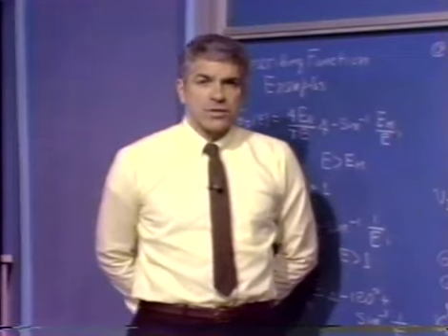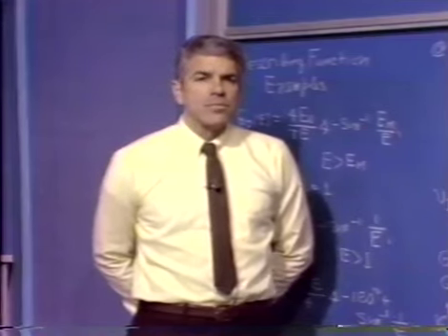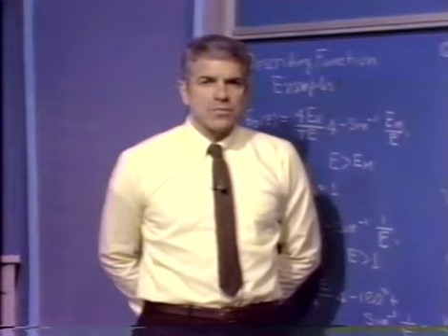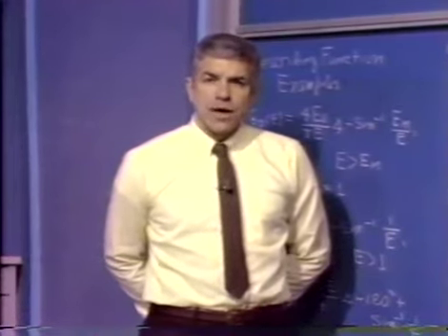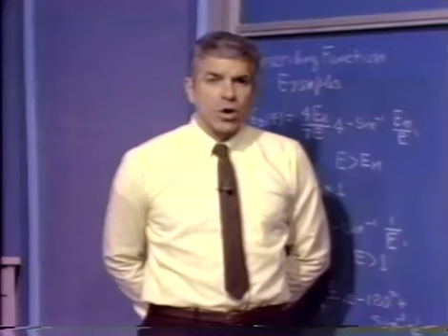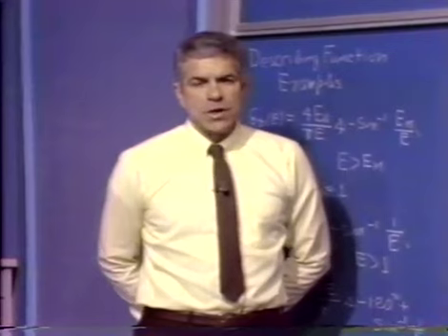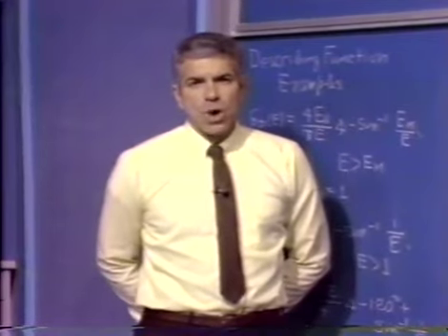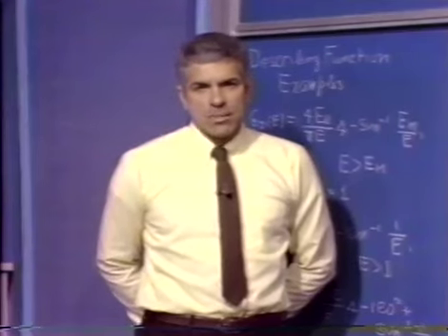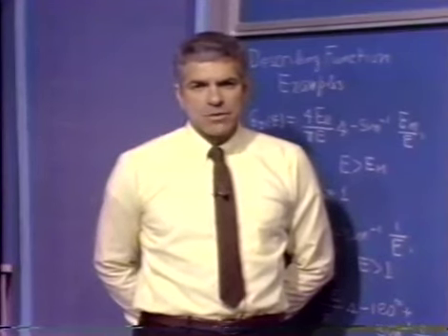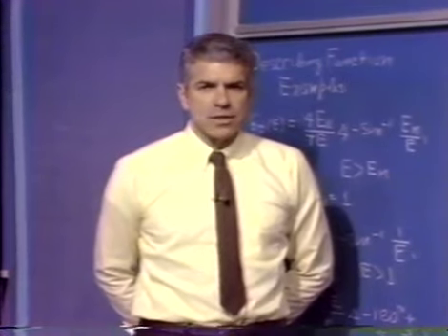The signal into the nonlinearity in this case is a triangle wave. The Fourier series for a triangle wave includes only odd harmonics, and they drop off as the square of the order of the harmonics. So the magnitude of the third harmonic is about 1/9, or 11%, of the magnitude of the fundamental. The fifth harmonic is about 4% of the magnitude of the fundamental, and so forth. So there's significant harmonic distortion in this case.